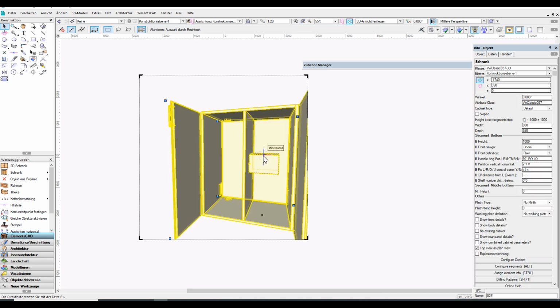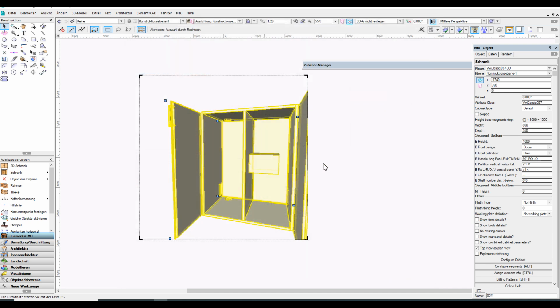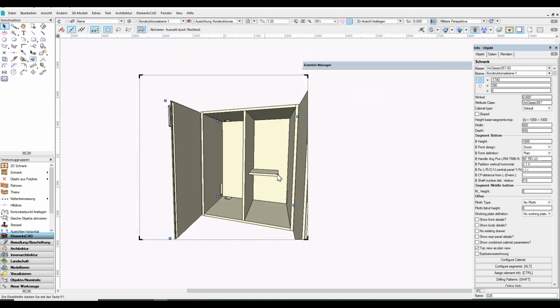Okay, we will go back again into the cutouts section. So we started from the beginning and from the end, and so I take the beginning here as well, and I insert 380 millimeters from the bottom. So now I have a panel.